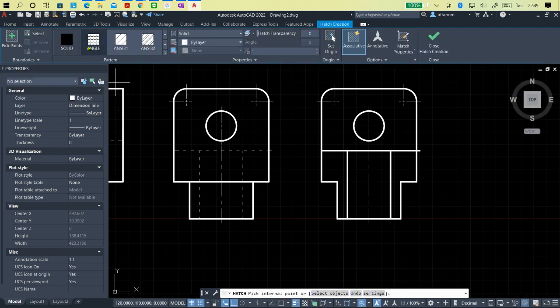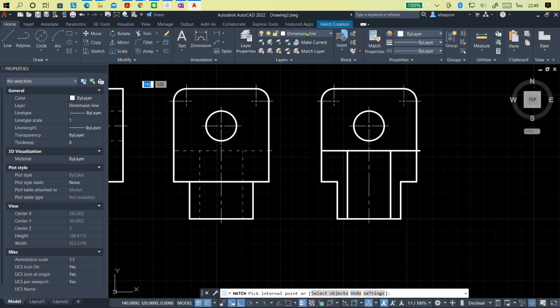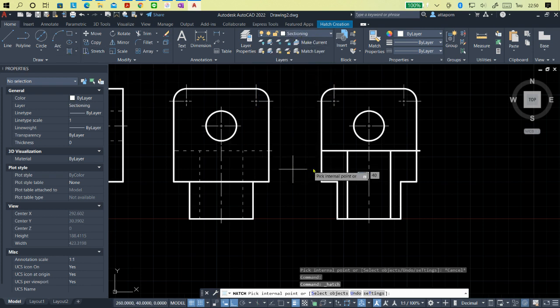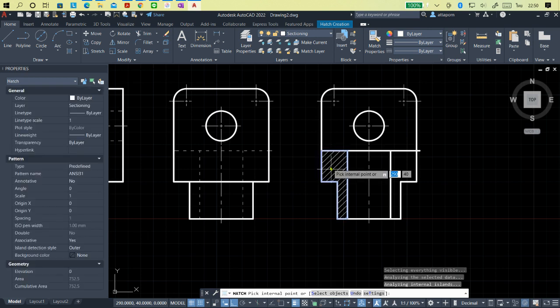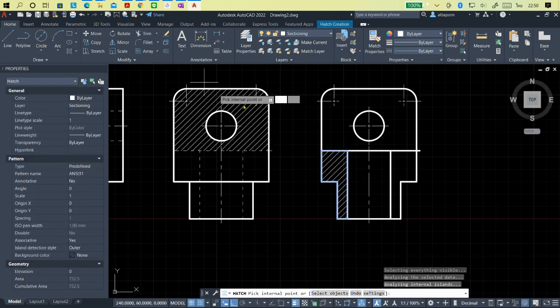and then hatchings, and then choose the style. For general, we use ANSI 31 here. Okay, and press here. But before you put it, you have to change to sectioning. Okay, sectioning. Hatchings here. ANSI. Sorry, I want to maybe click here first. Then no change anything.